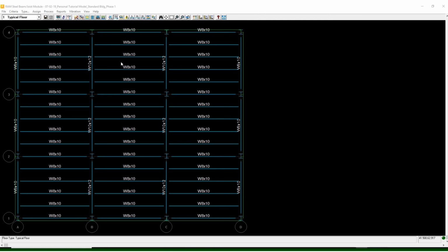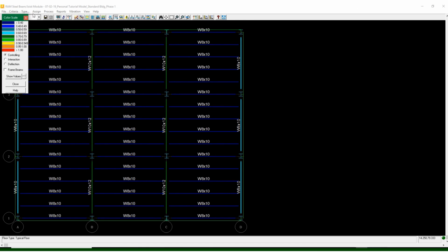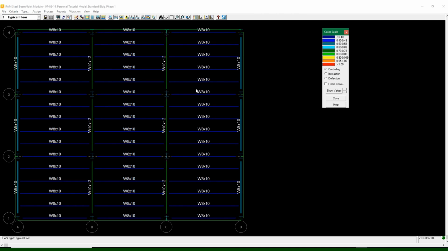As far as they're really flimsy, you're not going to have a beam that's 10 inches deep spanning 30 feet. It would not be easy to construct that beam. It would be deforming very easily just during the fabrication process. So those are not typical sections that we use, but based on the strength analysis, this is what is required.